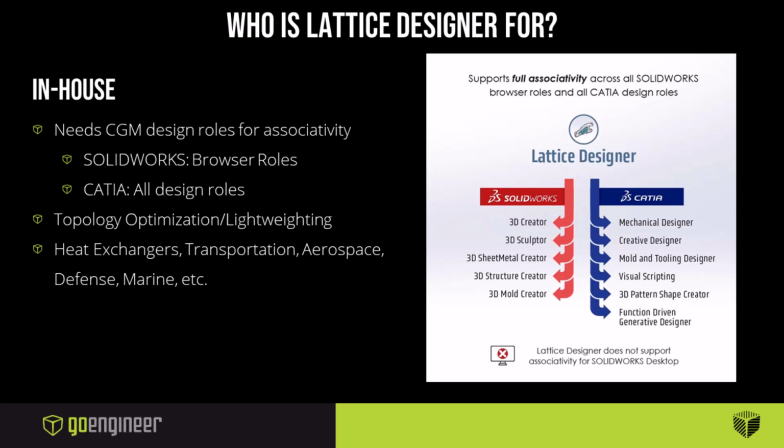Even if you are using SOLIDWORKS Connected, even if you are using the Design with SOLIDWORKS connector for 3DEXPERIENCE, parts made in desktop SOLIDWORKS will not maintain associativity with the platform. Desktop SOLIDWORKS parts can be imported into Lattice Designer, but they won't maintain associativity if you make a design update. That's not always a deal breaker for folks, but it is something that does need to be mentioned.